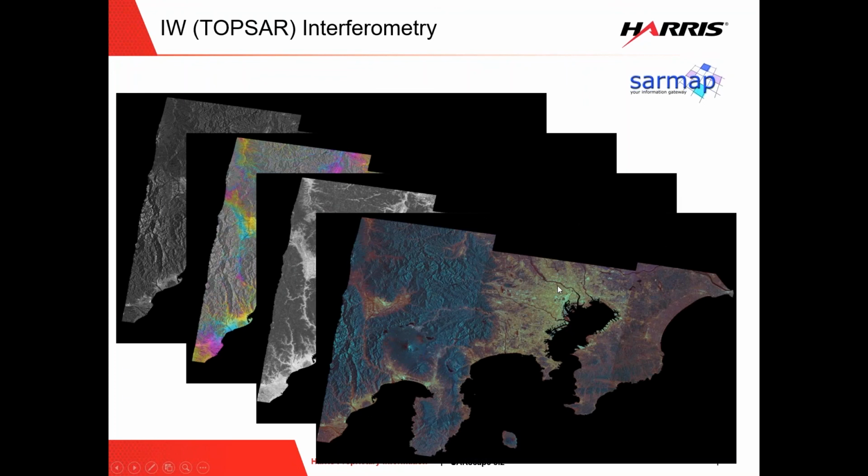And this is a false color composite of our complex coherence and our radar backscatter, again, where the green areas correspond to the vegetated areas, low coherence, good backscatter, and red and yellow areas, high coherence, strong backscatter, are urban areas.